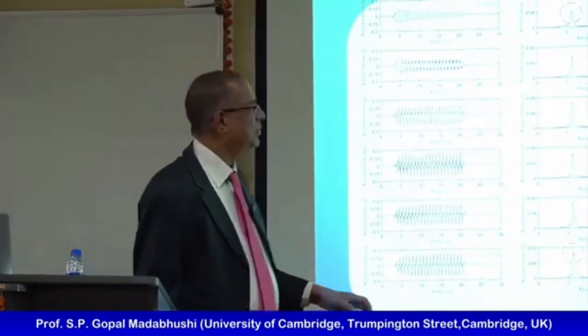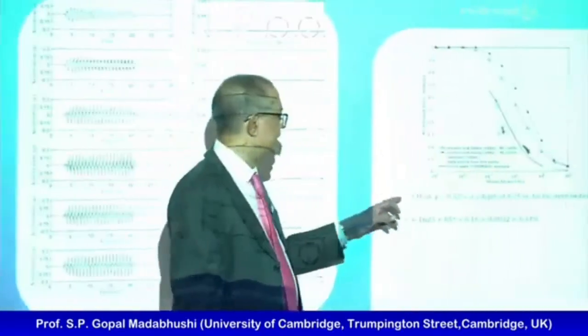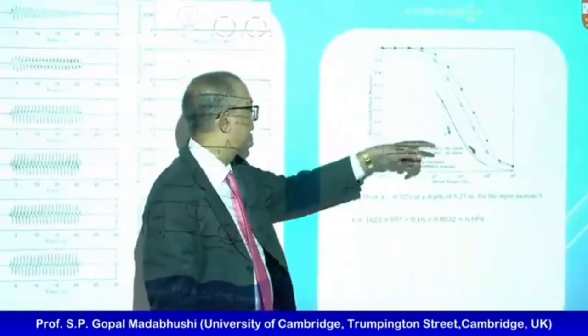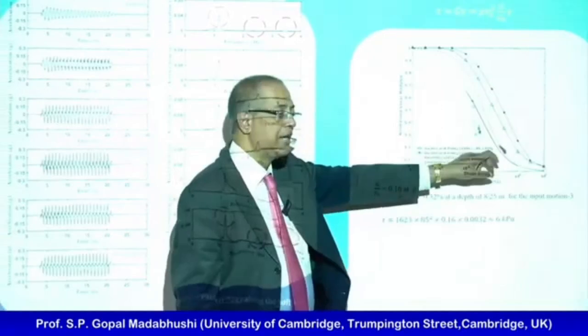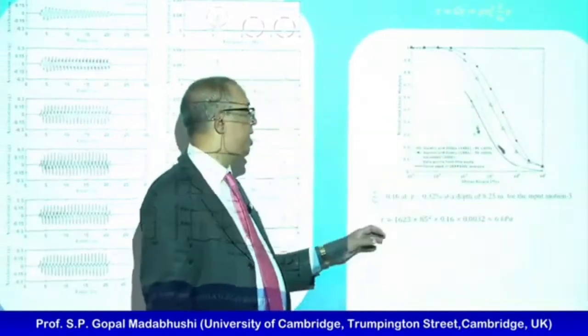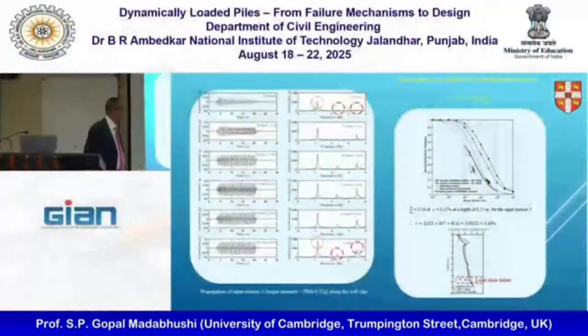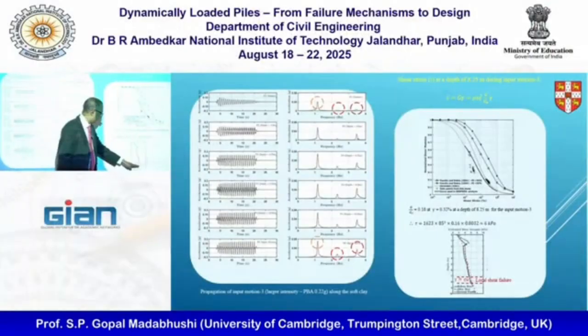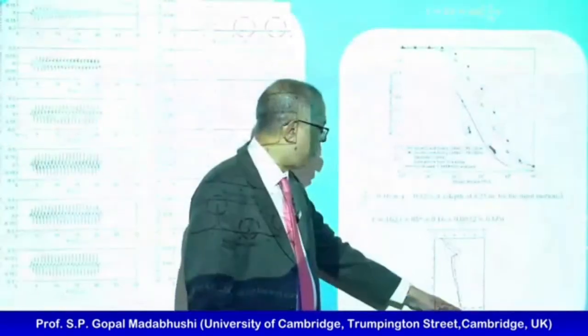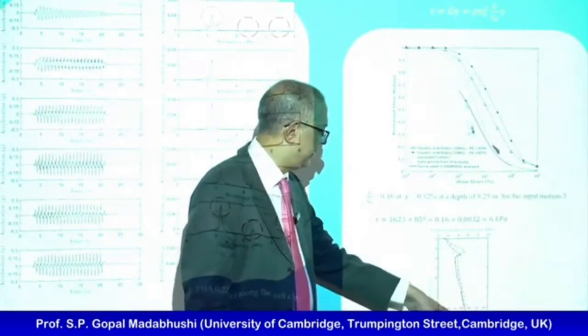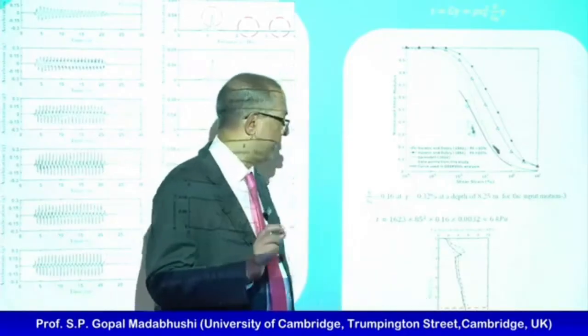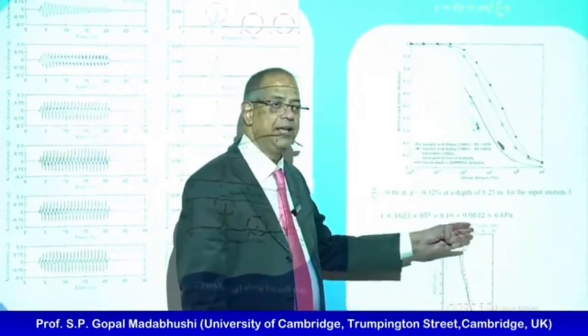Also, using these G over G naught curves, we could work out where our data falls, fit a line through that, and work out the shear stress at any depth. It's just a bit of maths, don't worry too much. But what we worked out is, if I look at a certain depth like this, above here my clay is not strong enough to carry the applied earthquake.